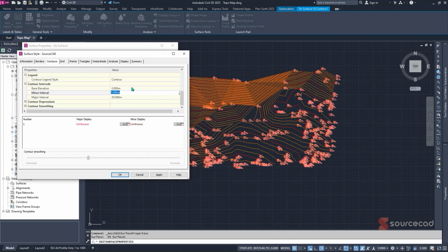And you can also specify your base elevation where the Z axis will start reading. So you can just leave it as 0, but you can specify how you want your very base elevations for your bands to be considered. For our case, we give it 1900, so you can just update it as 1900 and just like so.